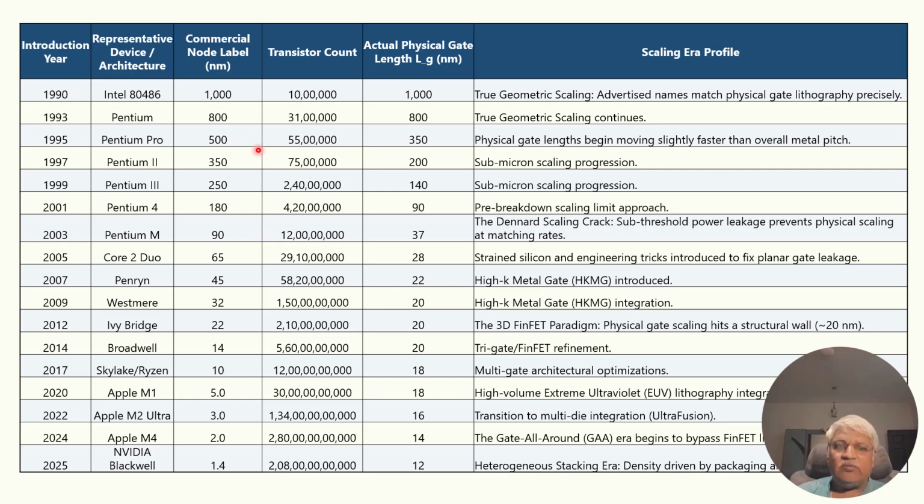So whatever we are talking about, 10 nanometer, 5 nanometer and all, the commercial node number, node name, and what actually is way different. Physical gate length is still way higher, because we are using FinFET or gate all around, or different architectures associated with it, multi-patterning in the metals and different possibilities.